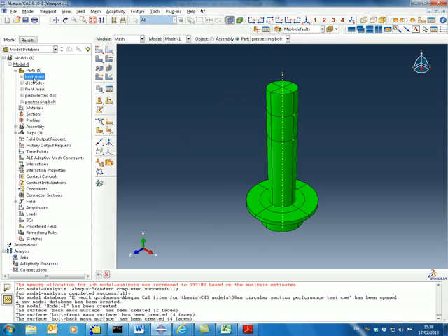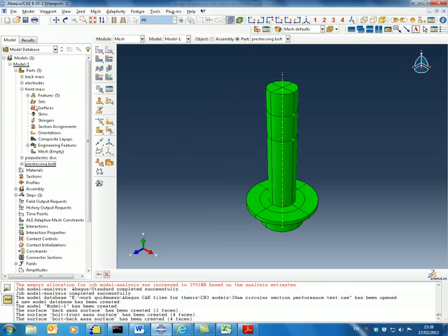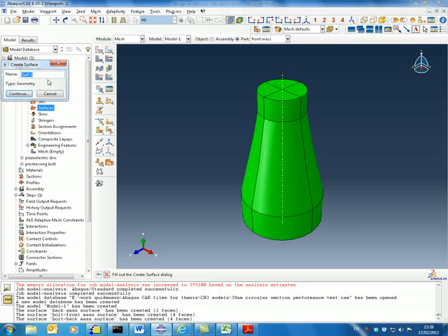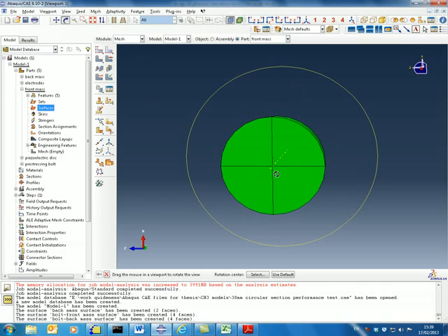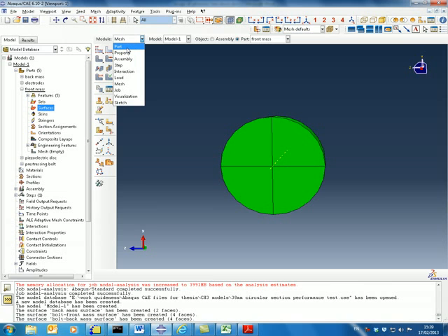We have created the back mass, electrode, front mass, piezoelectric disc, and pre-stress bolt. In the front mass, I forgot to create a section where the bolt goes inside the front mass and fits. This section will have the same dimension as the bolt, I mean the radial dimension.